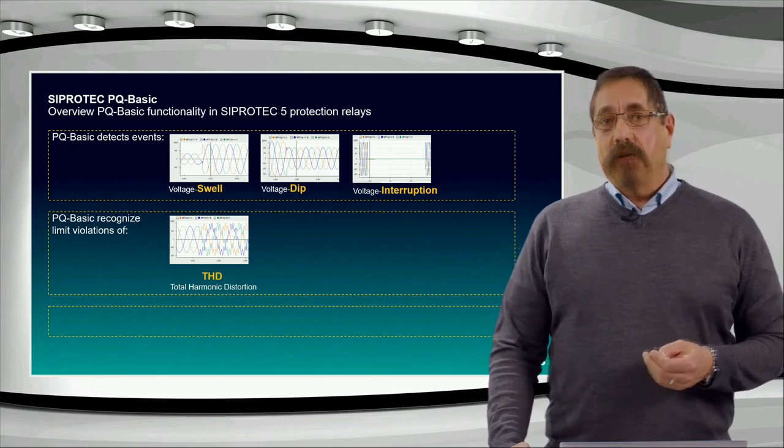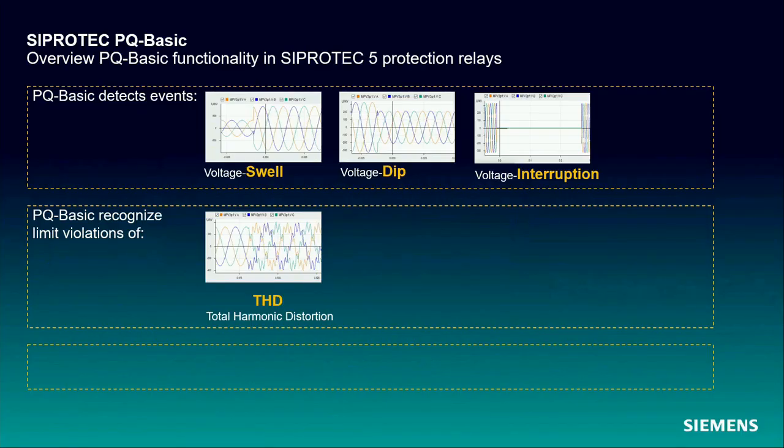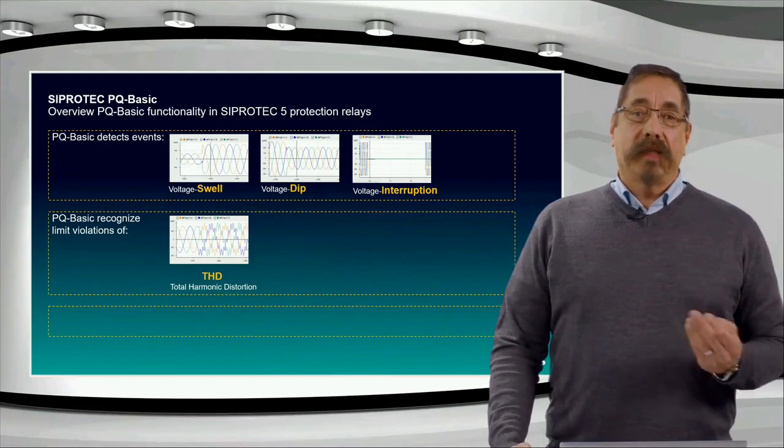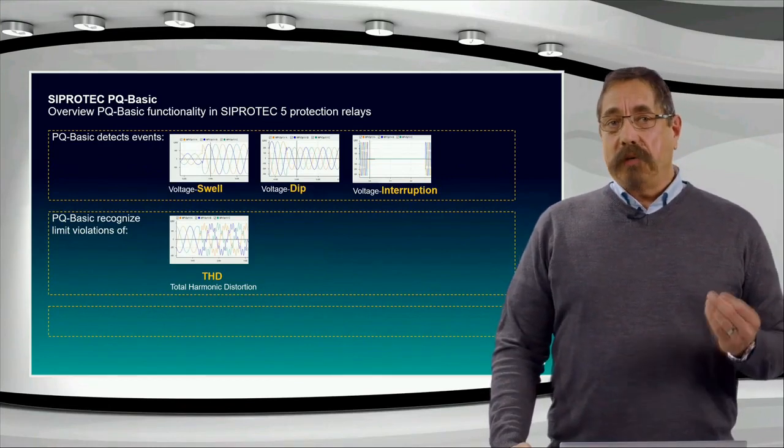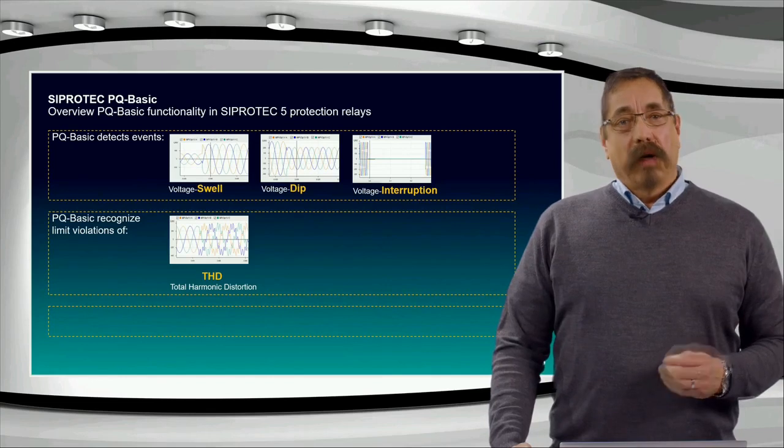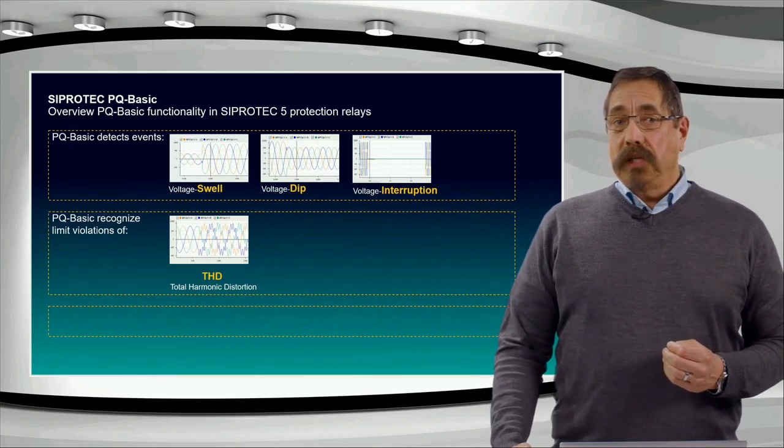The THD, or the total harmonic distortion, covers the harmonics of order number 2 up to 20. That THD value is an aggregation of 3000 10-cycle measurements. 10 cycles at 50 Hz is 200 milliseconds, and 3000 of them represent a 10-minute aggregation interval. When such an interval value exceeds the threshold limit, the PQ Basic mechanism stores the value and some more measurements for detailed reporting.